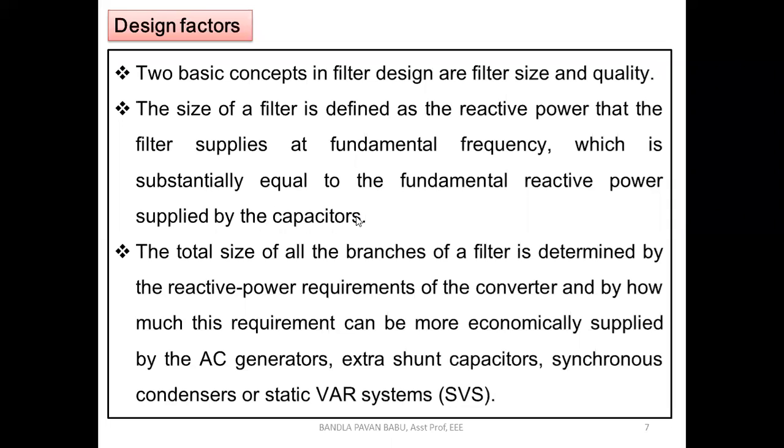Of course R is not mandatory, but any of the energy storing elements we need to prefer, either it is an RLC series circuit or RLC parallel circuit, or combinations of different LC components, either high pass filters or low pass filters or some other tuned filters, anything. Any of the filters can act as reactive power compensators based upon our switching techniques. Of course it depends on the switching techniques also. So that's what it means.